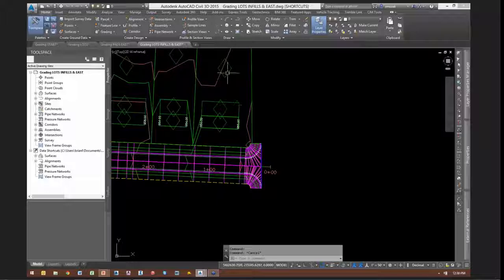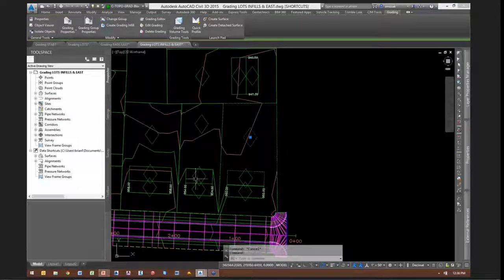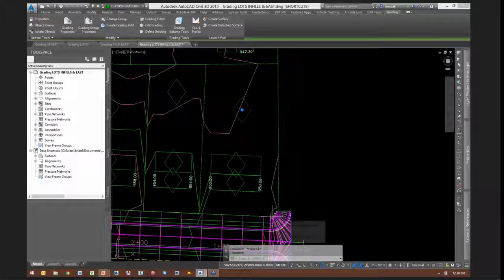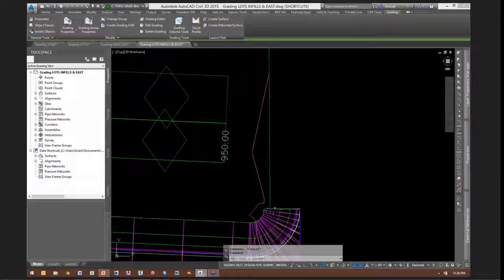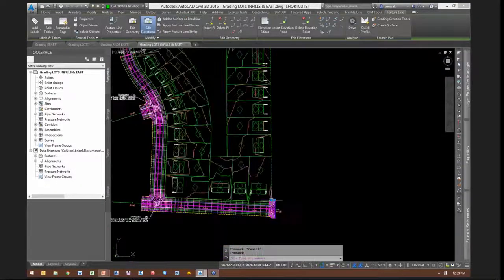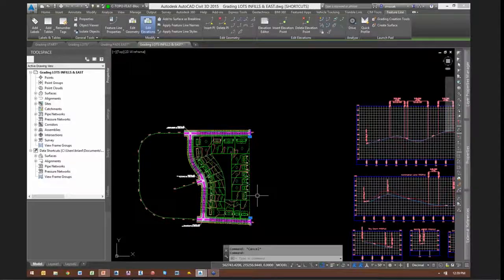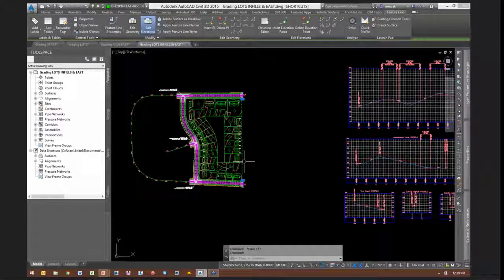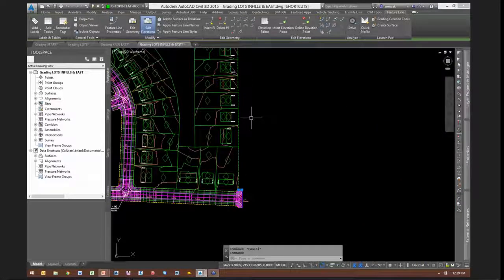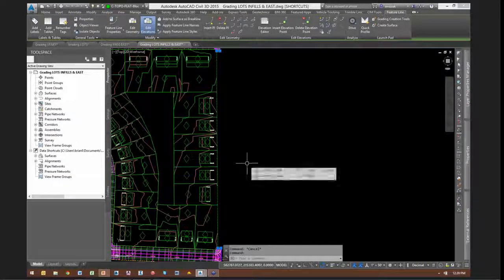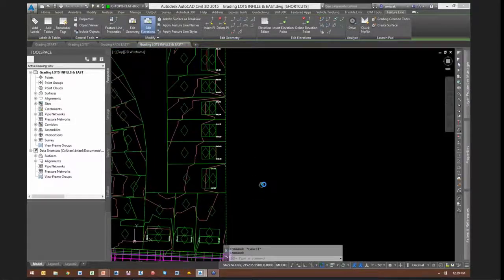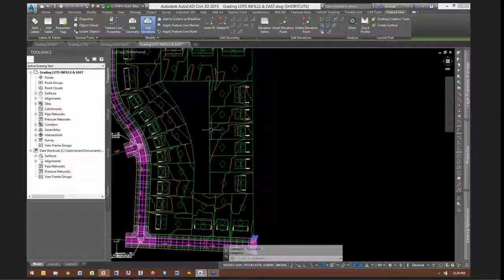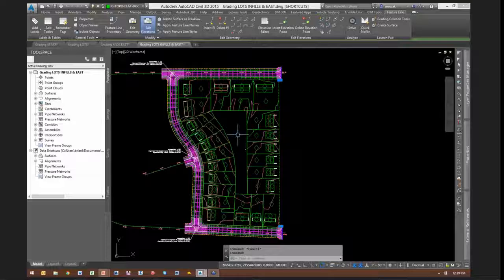And that allowed me to get this infill in here. Okay, so all those other ones work pretty well. These corner ones, they're a little tricky depending on how you end up finishing out your corridor. Okay, so this feature line along here now, this is just a constant grade along here. I could tie this into existing grade right here, or if I wanted to daylight from here and go daylight past the existing right-of-way, I could do that as well. So a number of options there, but this is how we're kind of tying it together.